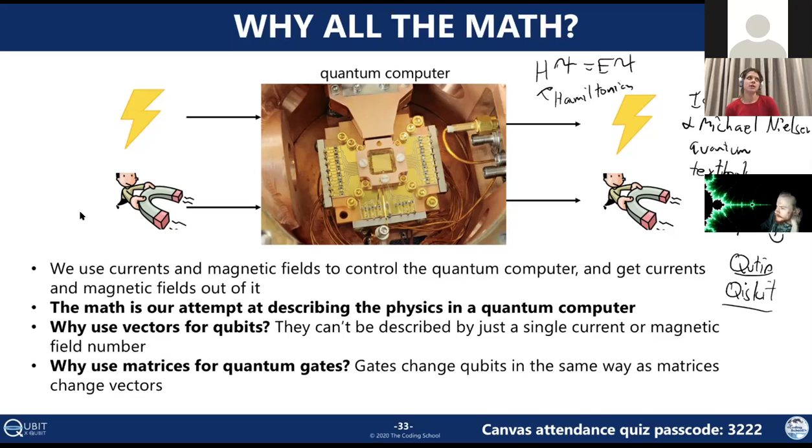But the superconducting material you use in it is not as expensive. We actually use aluminum, which is only superconducting below about 1 Kelvin, which we don't care about because we're in a dilution refrigerator where we operate at tens of millikelvin. But if you want a high temperature superconductor, then that's more expensive, I think. But you can also make your own if you have a chemistry lab, I guess.